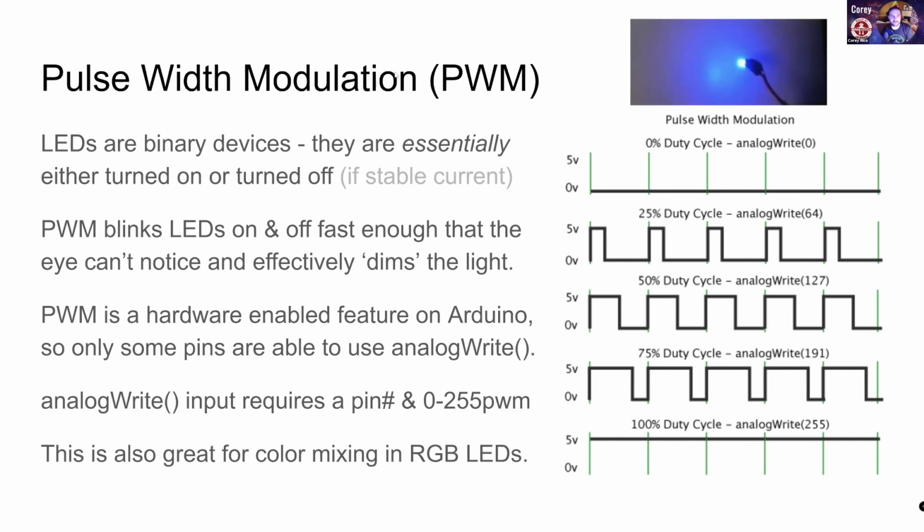Voltage control of brightness is a little trickier. It depends on what exactly you mean, but pulse width modulation is simulating having different voltages, is one way that it's often described. I don't actually love that description. But another way to think about it is that if I put in a 50% duty cycle, which means half the time it's on and half the time it's off, for this 5-volt level, it's kind of like I'm giving it 2.5 volts. So it's kind of like I'm half powering it.